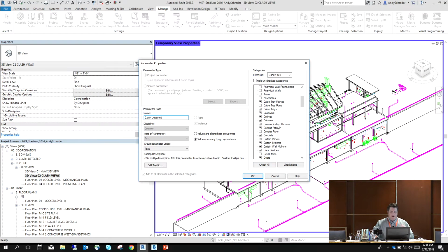A cable tray run is fittings and cable trays that are put together into a group. So if I've already got them independently, I don't need that system, that run. So you'll see with the cable tray runs, the conduit runs, the duct systems, I don't need those because I've already picked out those parts independently by having duct accessories, duct fittings, and ducts.